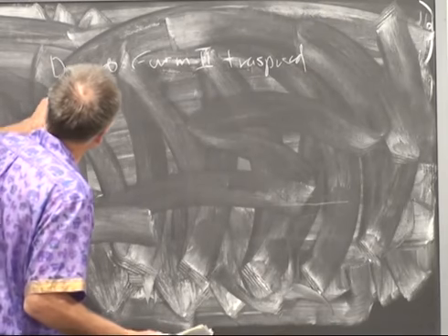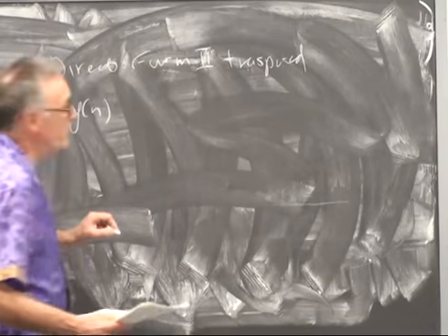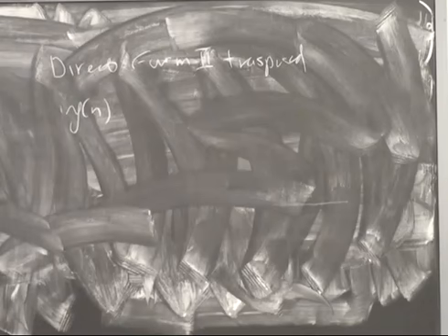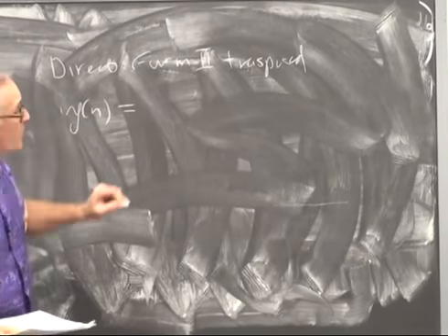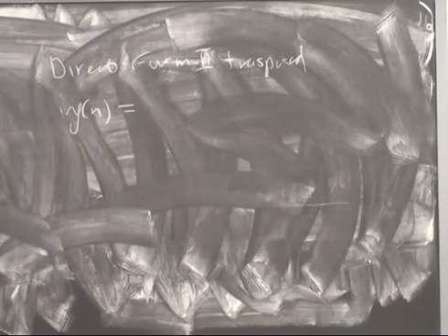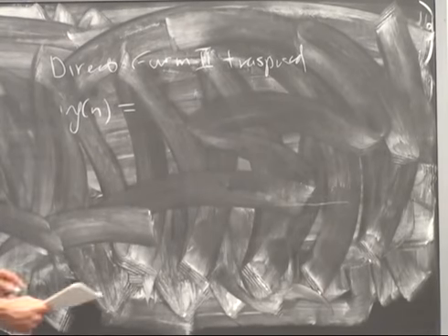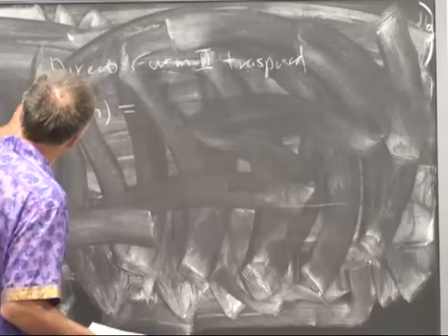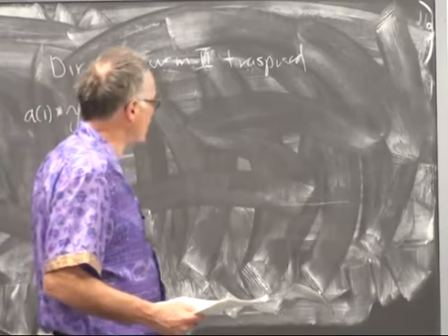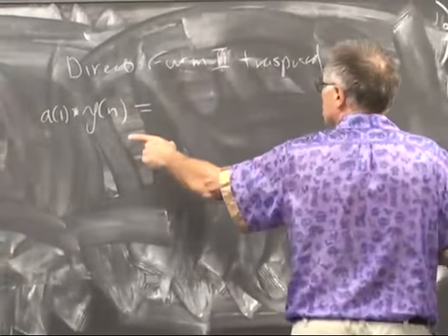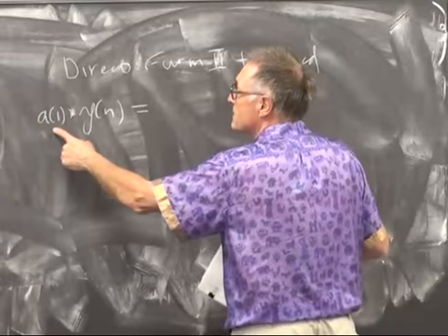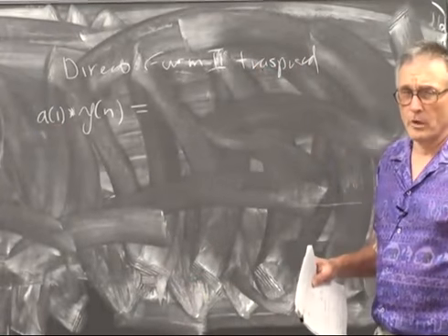If we have some new filter output y[n], we want to compute the new filter output as a linear combination of past samples. We're actually going to put a coefficient in front of y[n]. MATLAB always sets this to 1, but you might not want to.